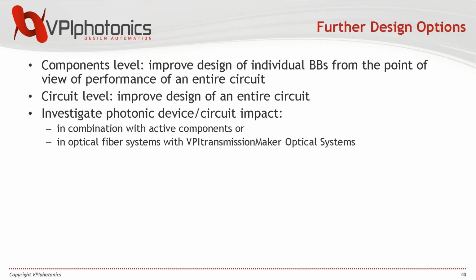And finally, just a seed for further design options, which are really rich. Probably you'll need to go back to component level and change your design, change the geometry of your components. Probably you need to think about changing the architecture of your circuit. A simple example of what it could mean: we had these inner couplers with air gap width in between, but probably you should switch to MMIs, to couplers with a silicon bridge between coupled waveguides. This kind of analysis could also be done.